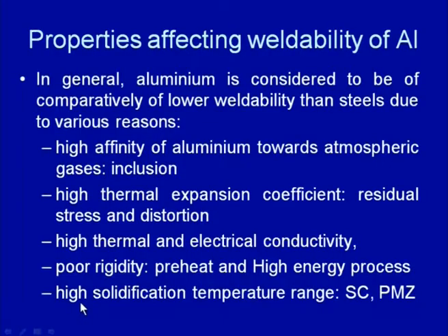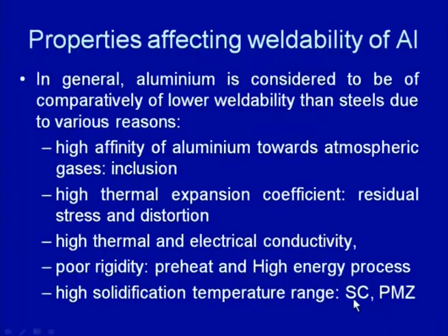And then, high solidification temperature range. In most of the aluminum alloys, when alloying elements are added, the solidification temperature range increases, and this increase in solidification range increases the tendency of solidification cracking, and cracking in the heat affected zone due to the partial melting effect in some areas, especially close to the fusion boundary.